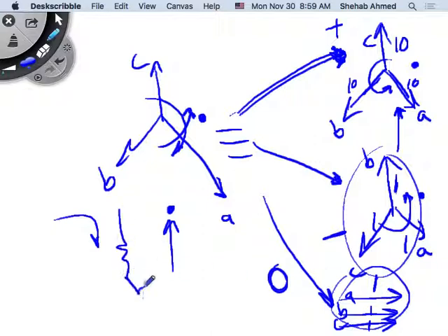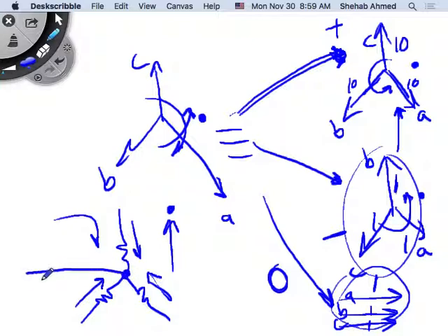Right? So if you apply them to a three-phase system, these are three-phase voltages, you will apply them to these three resistors. These are all in phase. They're not 120 degrees apart. So what will be the sum? 0? It will not be 0. It will be something, because these are all three in phase. They will cause current. So it will not be a balanced system either, right? This will be like plugging the motor, like applying a field in the motor that is stationary, right?